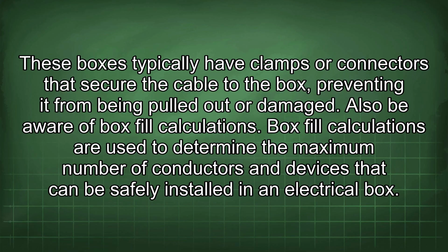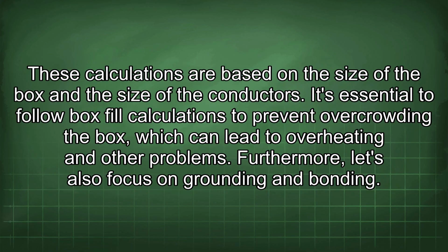Box fill calculations are used to determine the maximum number of conductors and devices that can be safely installed in an electrical box. These calculations are based on the size of the box and the size of the conductors. It's essential to follow box fill calculations to prevent overcrowding the box, which can lead to overheating and other problems.